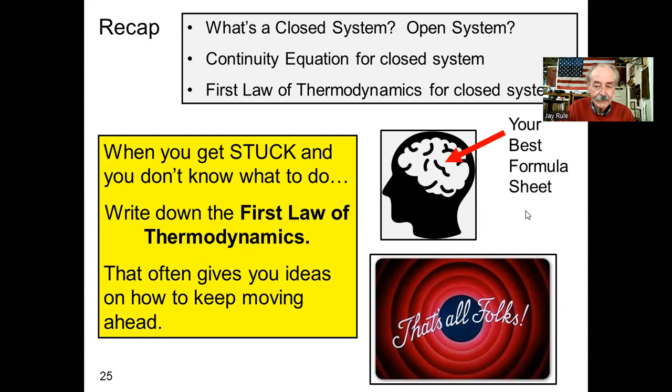Okay. One last idea. One of my favorite thermodynamics professors drilled this into our heads, and wow, did it pay off for us. When you get stuck on a thermal problem, you've read the problem, you got a little ways on it, you got your sketch, but then you get stuck. I don't know what to do. By far and away, if you write down the first law of thermodynamics on your paper and study it, many, many times you start looking at that, and very often it gives you ideas on how to keep moving ahead.